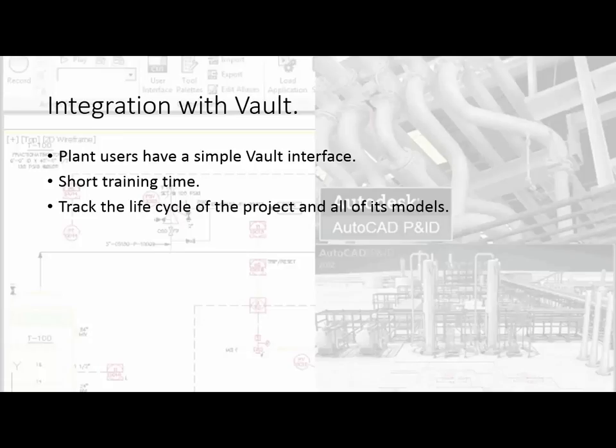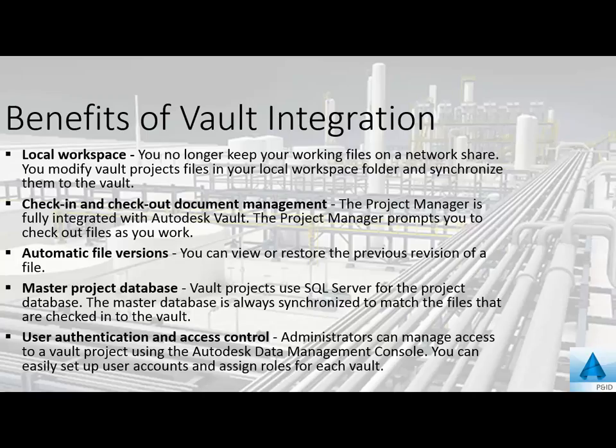If you're a Vault user, good news, there's great integration with Vault here. The plant users have a very simple Vault interface. It does not take much time to learn the Vault interface, and it allows you to track the life cycle of the project and all of its models. You get a local workspace. You can check in and check out. Great document management. Automatic file versions. You get a master project database, user authentication, and access control. All of these things can be beneficial to the project you're working on, making it much easier for more than one person to be involved in the project, even at multiple locations.